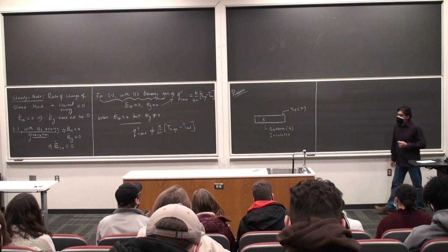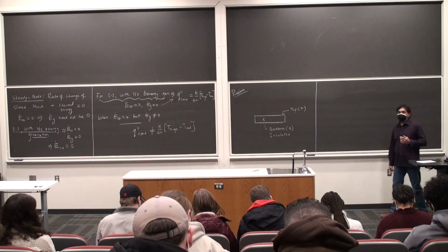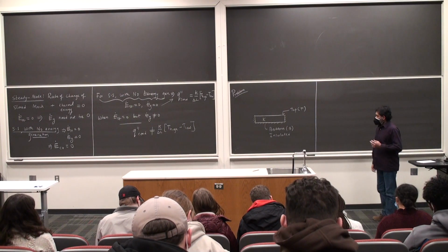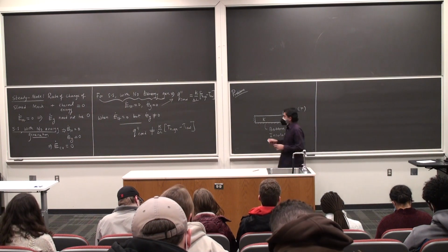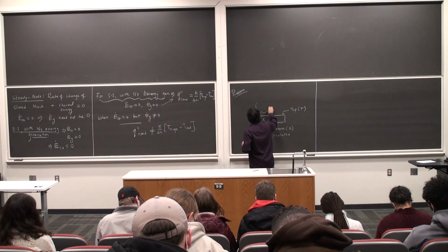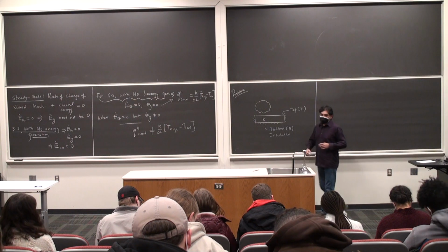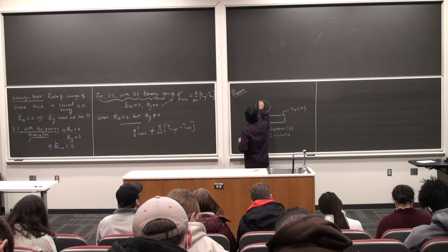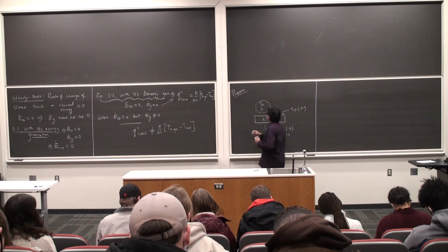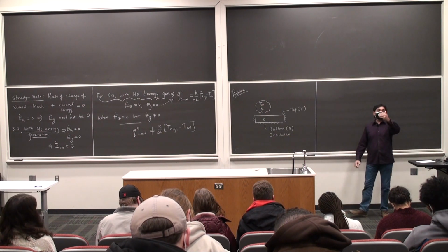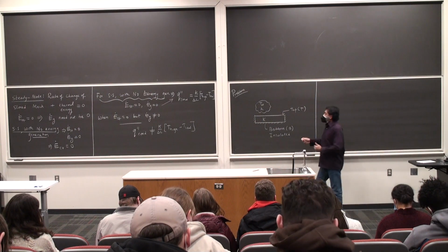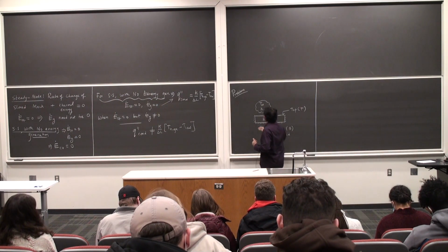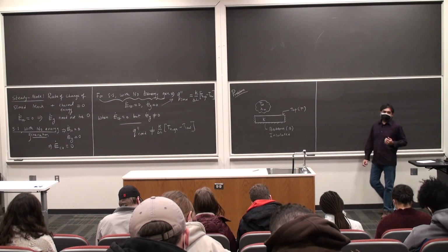Subscript is T. The temperature of the top surface is not known to us. You are told that there is some ambient air in bulk motion close to the surface, and the temperature is T infinity. The convection heat transfer coefficient between the ambient air and the top surface, let's say h suffix T, is given to us in the problem. I'm going to list all these variables.